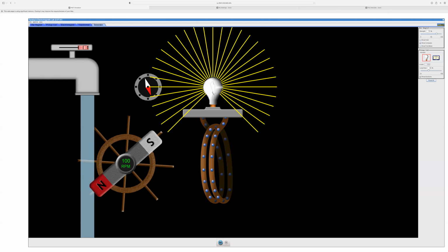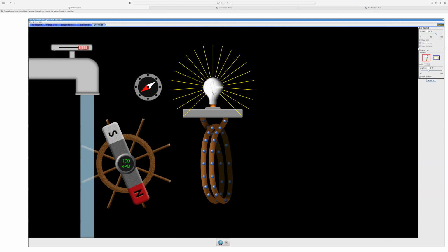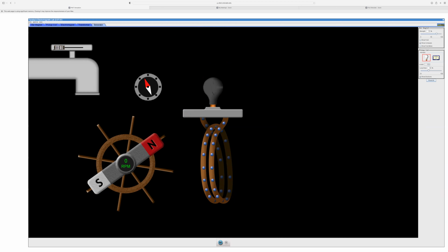Whenever you go to any electrical device and see, they would have written the voltage associated with it and the frequency across which it will be handled. For example, if you want any device to work in India, you need to design those devices at an RMS value of 230 volt. Have you ever seen the stabilizer of an AC with a display? If you have not, go home and observe. If you have, you will see the values varying somewhere between 220 to 240.